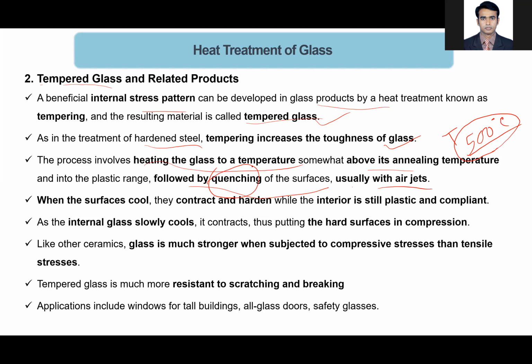The quenching does not mean that you are rapidly cooling to room temperature. There are many different ways to do quenching or tempering. For steel, tempering can be done in many different ways. For example, if we produce the austenite and then rapidly cool to 400 degrees Celsius and keep it at 400 degrees Celsius, this causes a different property than if we cool it directly to room temperature. So there are many different ways of tempering.